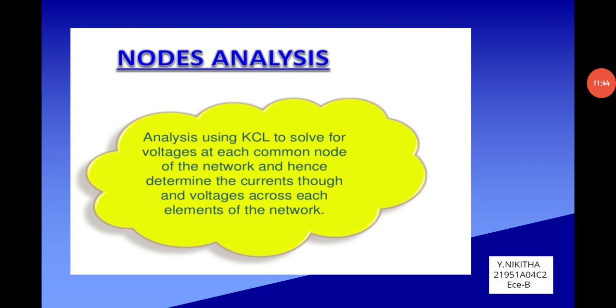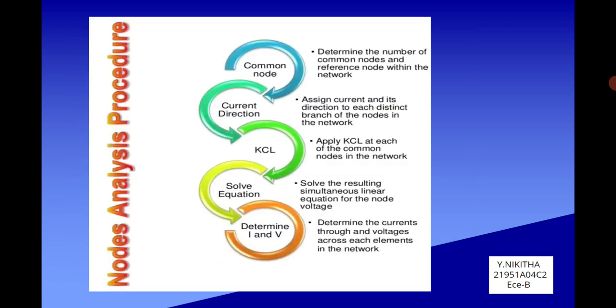Nodal analysis. Analysis using KCL to solve for voltages at each common node of the network and hence determine the currents through and voltages across each element of the network. Nodal analysis procedure: common node, current direction, KCL, solve equation, determine I and V.